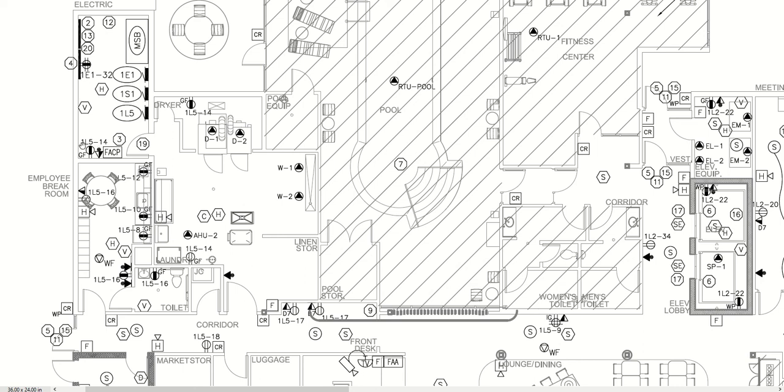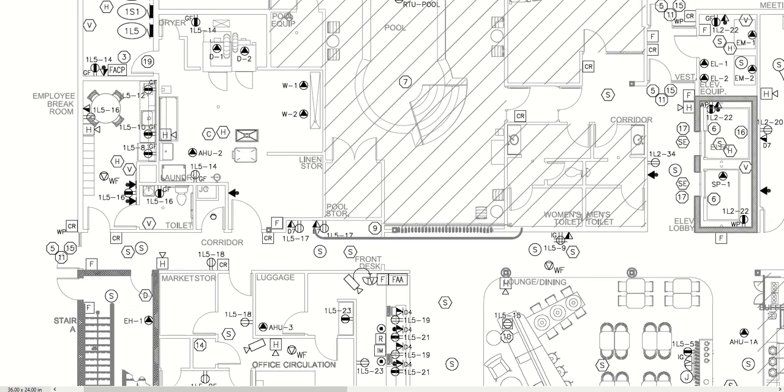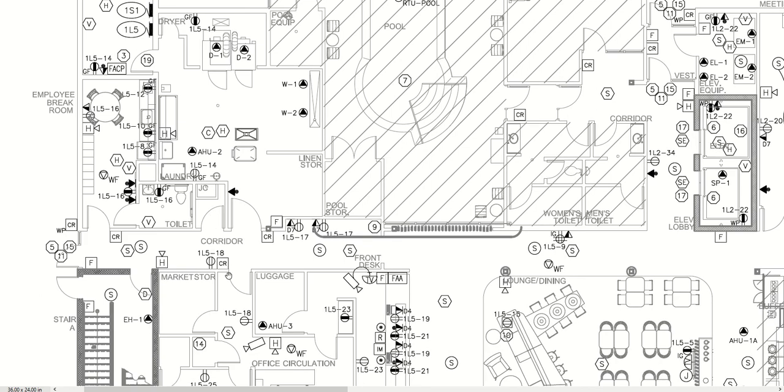And so the first digit in the panel name is the floor that it's on, so these are all on the first floor. The L usually indicates lighting panel, or lower or level panel. You can run outlets out of there as well. S was for site, so all the site power comes from this S panel. But your naming conventions can be whatever you want, but these are just what we picked on this project.